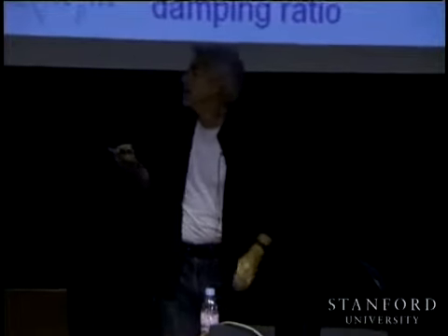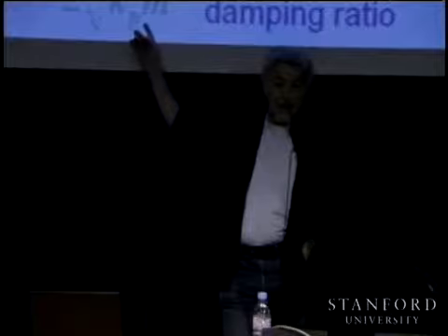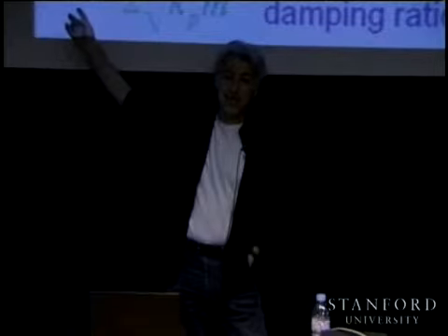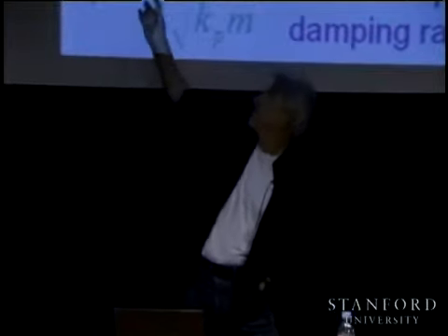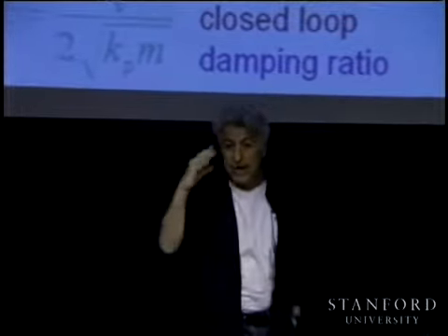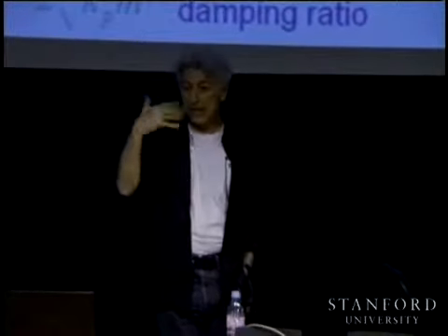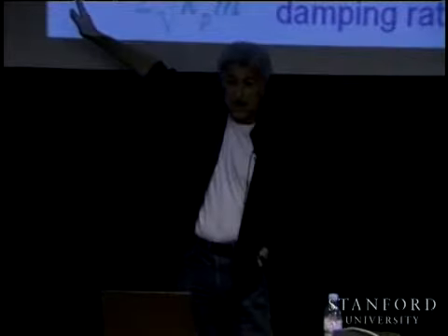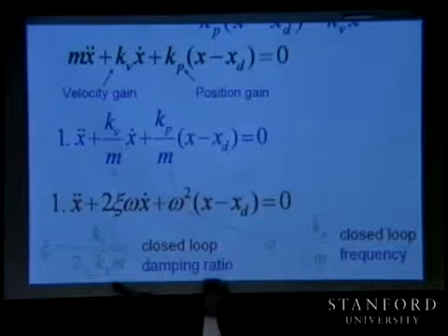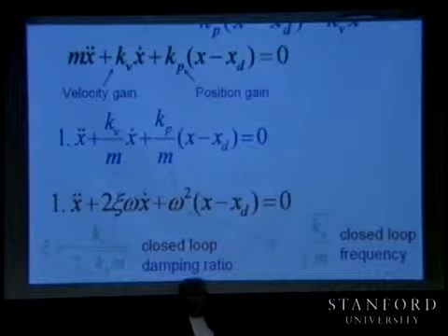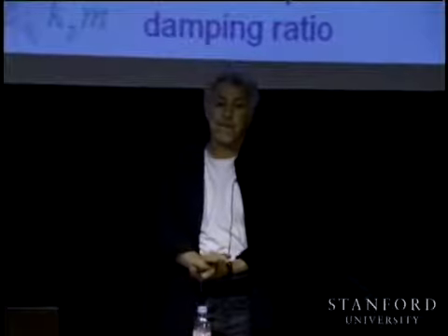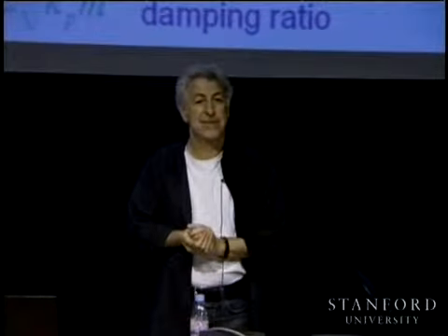So basically, if you already selected your Kp, and if you want a critically damped system, then immediately you can compute Kv from m and Kp, right? For that value of zeta. So basically, you are trying to set zeta. What about omega? So now we need to set Kp in order to set omega. And how do we set omega? Someone? Matthew.